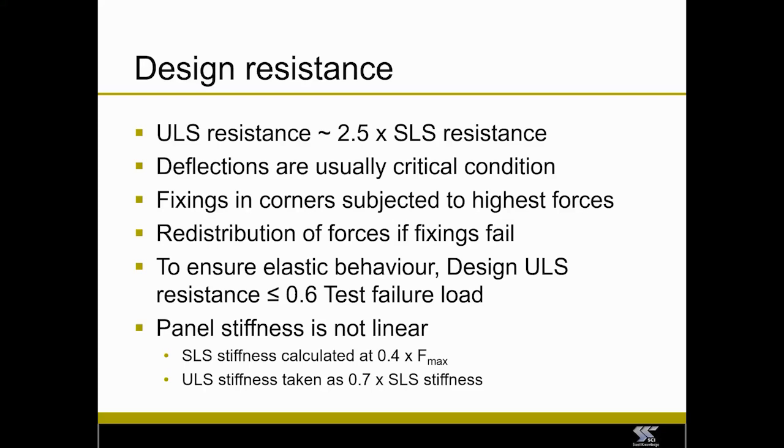Obviously, where the boards are fixed to the frame, you get the highest fixing forces at the corners, but then as those fixings fail towards the end of the test, forces are redistributed to other fixings around the perimeter of the board. So it's quite a ductile failure, or quite a long tail to the force deflection curve that you get from these tests.